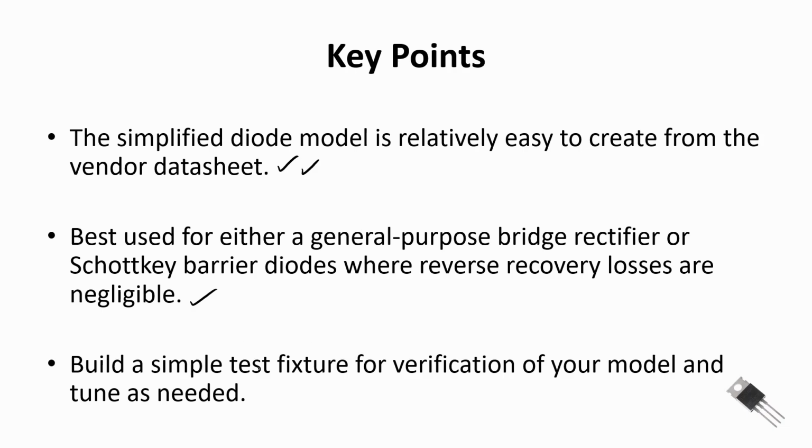And then finally, I always recommend build a simple test fixture like I did here and verify your diode model, and then tune it as needed to fit that vendor's data sheet. Hope that helps you with building up some simplified diode models in LTspice.